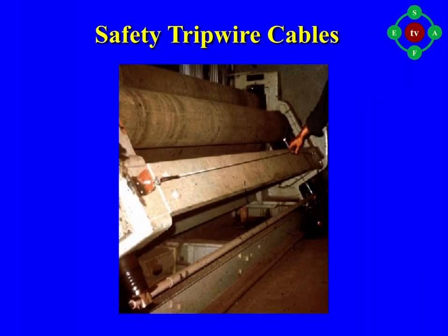Safety tripwire cables. Device located around the perimeter of or near the danger area. An operator must be able to reach the cable to stop the machine.